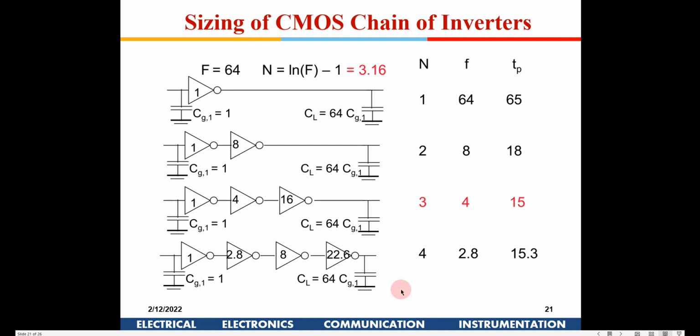In the next class we will see how to make layouts of circuits and stick diagrams and things like that. We will see that W is a variable. In analog circuits, even L we do change. In digital circuits, L we keep constant. In the advanced VLSI course also, you will have to change W in many cases for the circuit to function at all. When we see SRAM also, we will see that W is a variable which needs to be changed for optimizing the circuits.